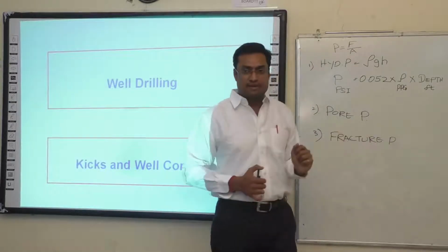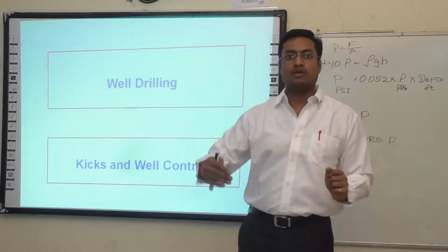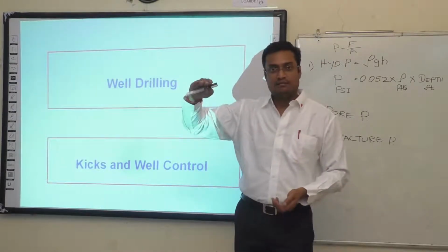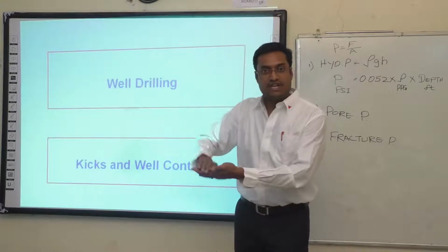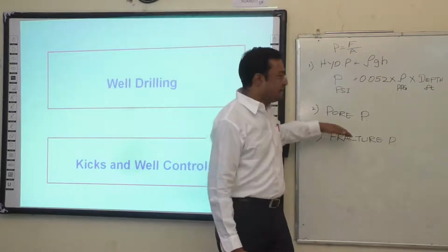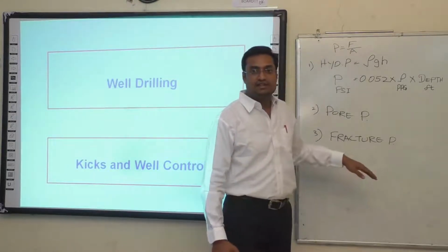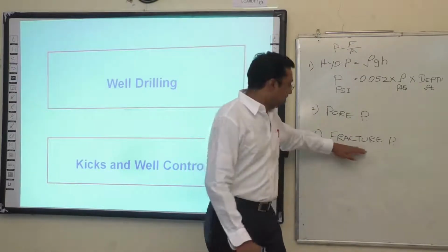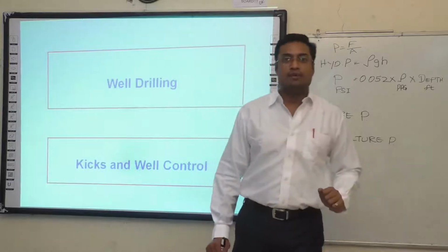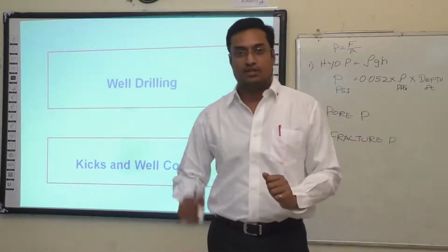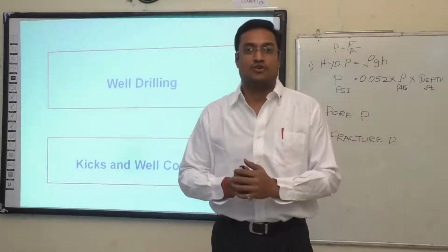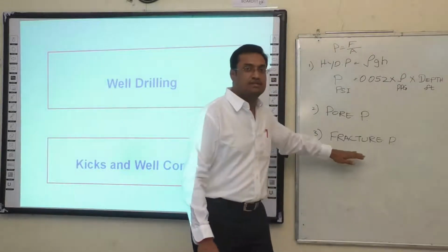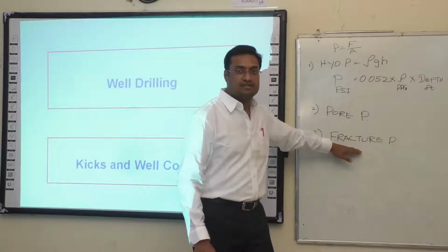So this fracture pressure is a component of the pressure we apply from the surface, plus the hydrostatic pressure caused by the fluids, and the pore pressure. This fracture pressure is very, very important to bring the well under our control. So we should not allow the formation to fracture.